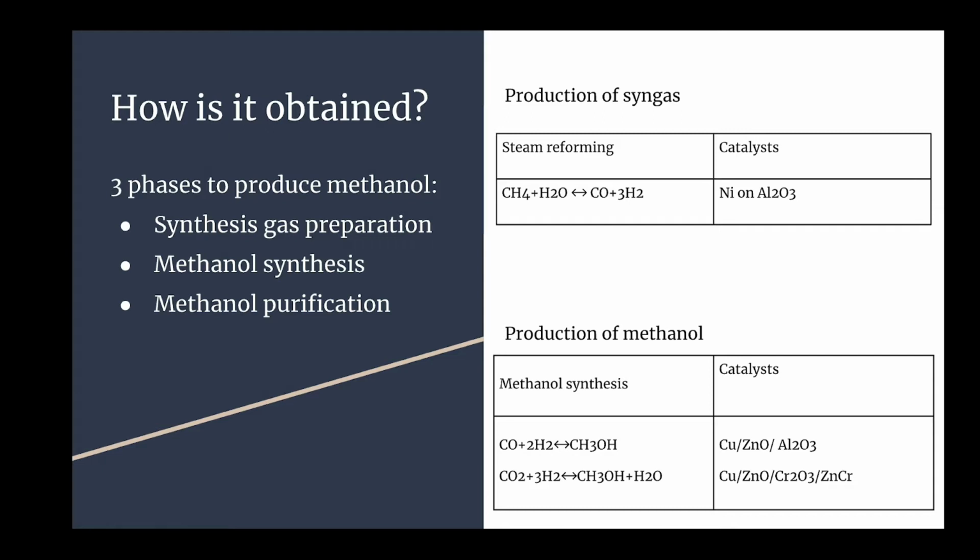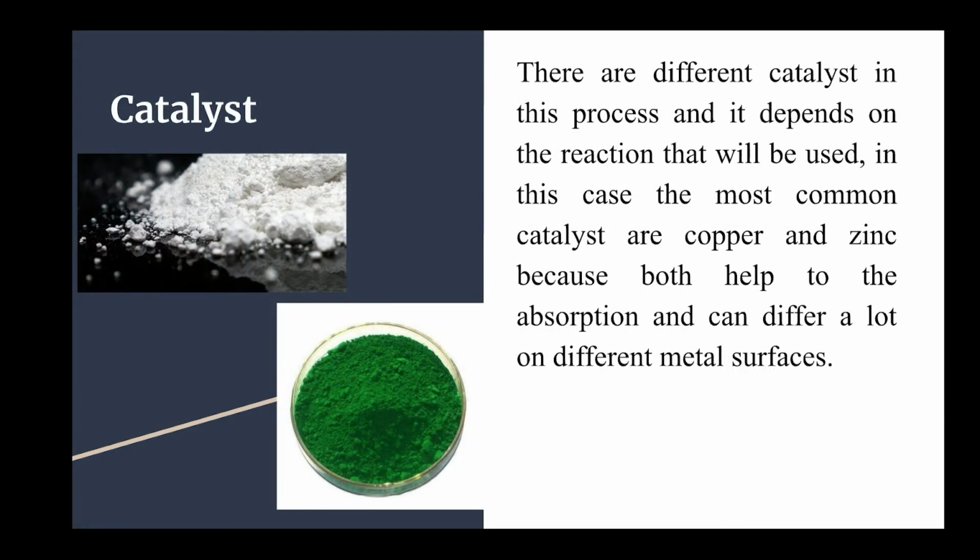Also, a world-scale methanol plant produces 5,000 metric tons per day. Normally, the reaction occurs at a temperature of 300 to 400 degrees Celsius and a pressure of 200 to 300 atmospheres. The catalysts used are zinc oxide or chromium oxide. The synthesis gas, the raw material, can be obtained in different ways. The different production processes differ from each other precisely because of this.